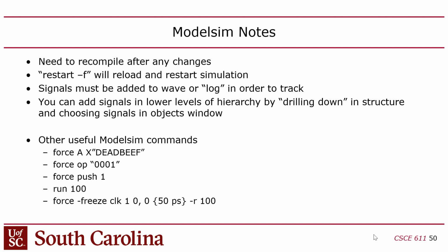And they might say, holy cow, that's a fast circuit if it's running in 100 picoseconds. Yeah, but it's irrelevant. The units are irrelevant because we are not modeling circuit delay, because circuit delay comes from capacitance and resistance in the circuit. Capacitance comes from just the fact that you have metal that sits on top of a dielectric, right, on the chip. That creates capacitance. So the longer and the fatter and the wider, the more area your wire has, the more capacitance, and the longer the wire is, the more resistance it has. And of course, transistors and active devices have capacitance and resistance, and all that contributes to delay.